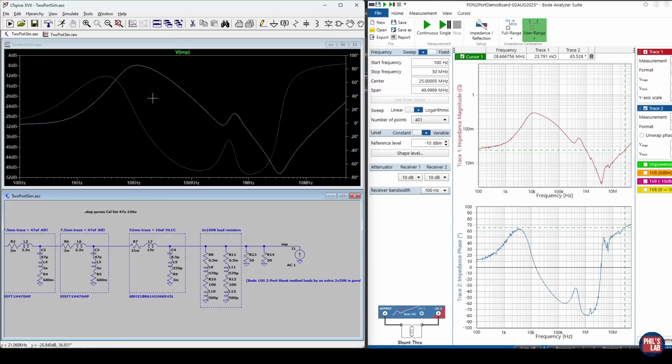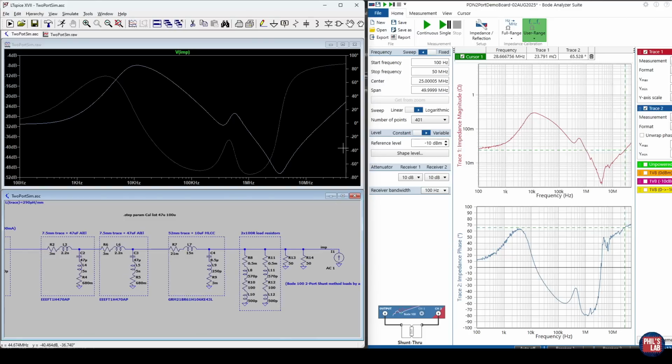For the most part, there are tiny bits of offset, of course, and higher resolution in the actual measurement than our lower fidelity SPICE model we have here. But I think it demonstrates quite nicely that even with a simple simulation, you can approximate these PDN curves, and also how to then show the impedance versus frequency using LTSpice.